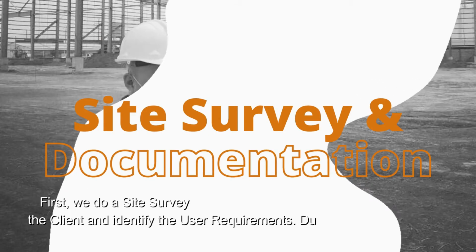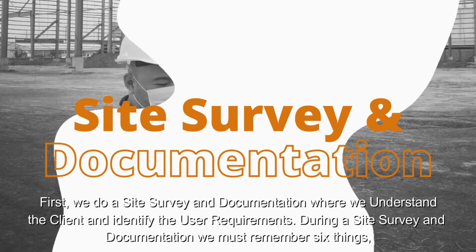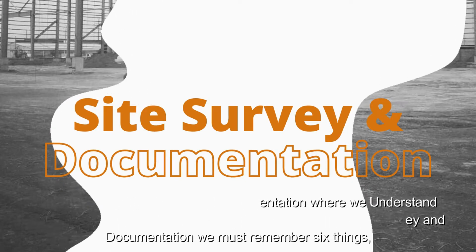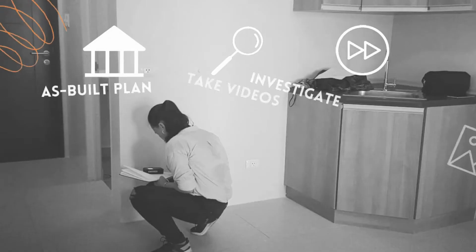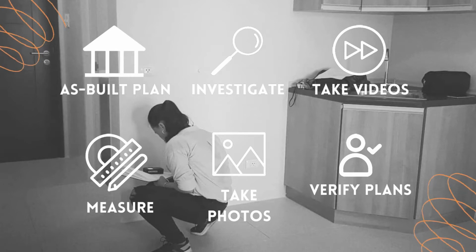First, we do a site survey and documentation where we understand the client and identify the user requirements. During a site documentation, we must remember 6 things: as-built plan, investigate, take videos, measure, take photos, and verify plan.